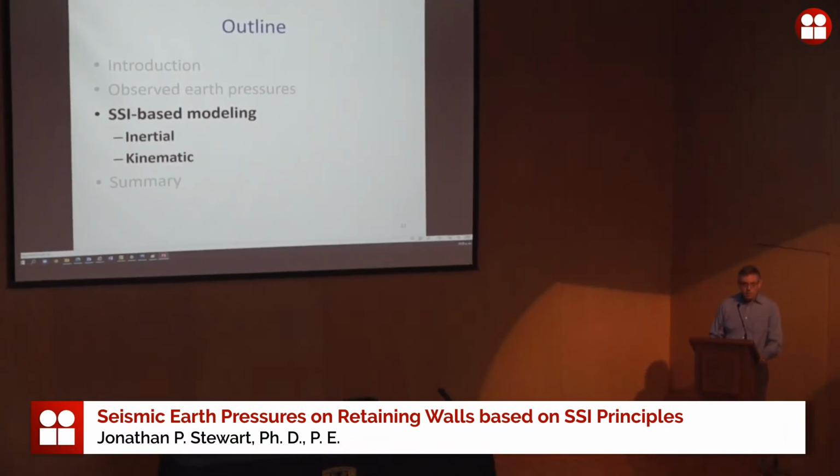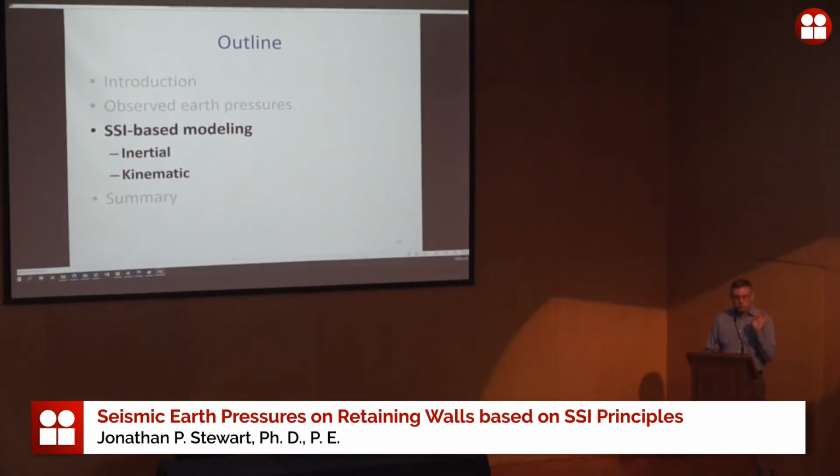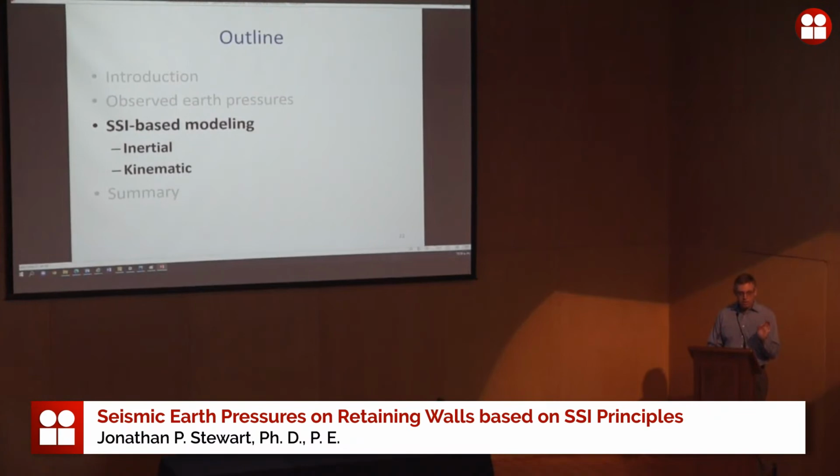And there's a lot of stuff that's going to follow here now, but there's one most critical point that I'm going to tell you right now, and I'm going to tell you it again a bunch of times in the next few minutes. And that is, what is it that actually causes pressures to develop against a wall? When you get right down to it, there's a very simple principle that's at play here. If the soil and the wall are moving differently from each other, you're going to get pressure.